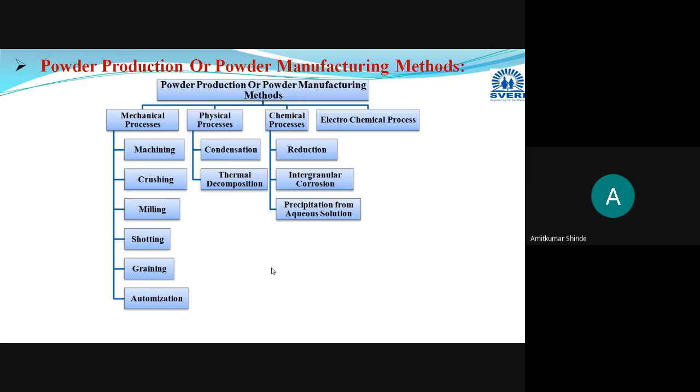Okay, and at the end you can separate that powder. Okay, simply I will repeat it again. In the milling operation, the material whose powder you are going to manufacture is taken in the form of a rod or a bar or a plate, along with hard rod-shaped mills or ball-shaped mills, or disc-shaped. Okay, just hard balls or hard discs will be there along with that source material, and these two will be taken in a stainless steel drum, and that drum is rotated with very high speed.